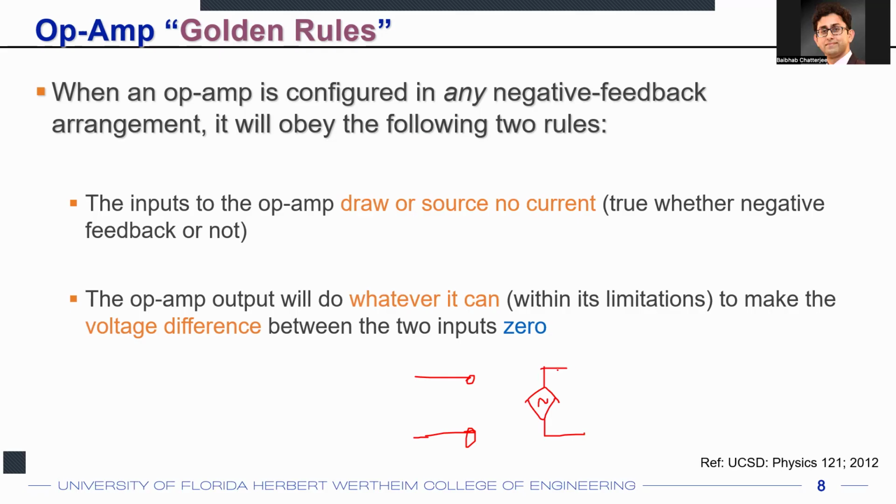And this voltage controlled voltage source, if it has zero output impedance, let's say this output impedance Rout or RO is equal to 0. And then you connect it to some kind of a load at the output side. Now, if your RO is equal to 0, then all the voltage drop will happen across this load resistance RL, right? There would be no voltage division between the two.